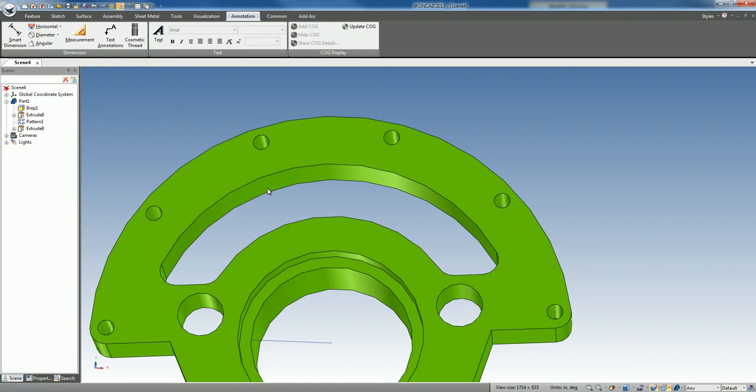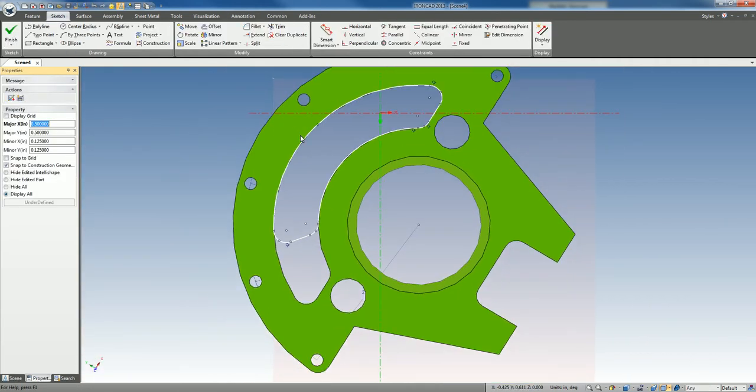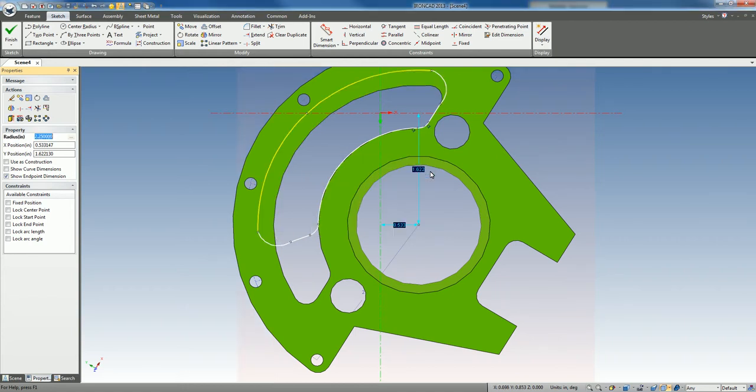What if we want to make another modification that's easier? For example, what if we wanted to make this radius change a little higher? Well, yes, we could go into the sketch, edit the cross section, and do simple curve properties. Just make that 2.25, make it a little bit bigger. You can see the change. And repeat the same thing for the other side, but you'll notice there were no tangencies here. It didn't know what to do with this geometry.